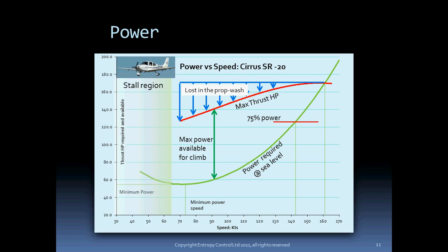But say you were flying at 75 knots, what happens? The aircraft slows to say 68 knots, giving you the same comforting initial fillip as it slows down, but then because you are now behind the power curve, it actually starts to slowly sink. If you're busy and distracted enough, maybe you try raising the nose more, and the aircraft sinks more, and you're very close to stalling speed. This is the way accidents happen.